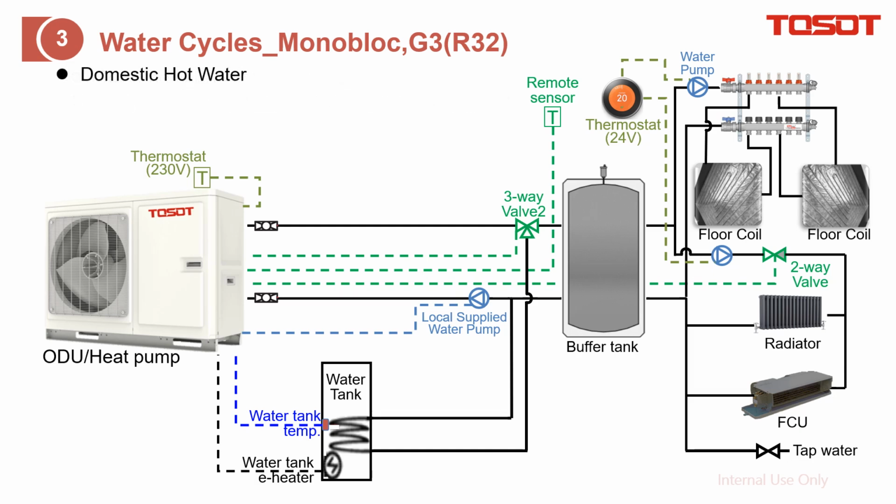When you select domestic hot water mode, based on this three-way valve, we conduct the hot water to the water tank to heat up the DHW and then go back to the Versatility. And attention, this water is not directly for DHW. You need to heat up the DHW. Okay?